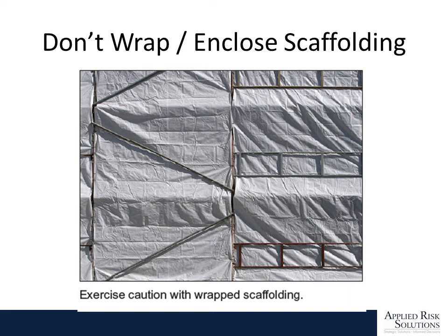Don't wrap or enclose your scaffolding. Scaffolds are made to accept forces in the vertical direction, up and down. They're very strong that way. When you wrap them, and the wind blows, tremendous horizontal forces can be applied to the scaffolding, and it can rip it and pull it down.